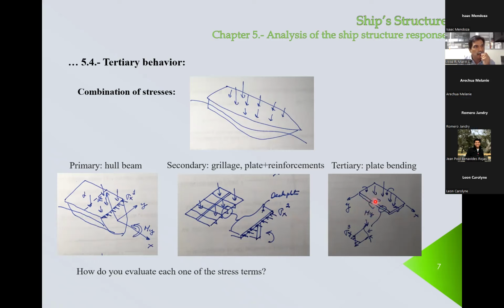Good morning, doctor. And thickness and the moment. Yeah, but I'm interested in the moment. What information do you need to calculate the moment? Moment Y. That's not right. My question is, what information do you need to calculate the moment? Maybe if we use Timoshenko's table, but what information do you need? The pressure and the dimensions of the plate.